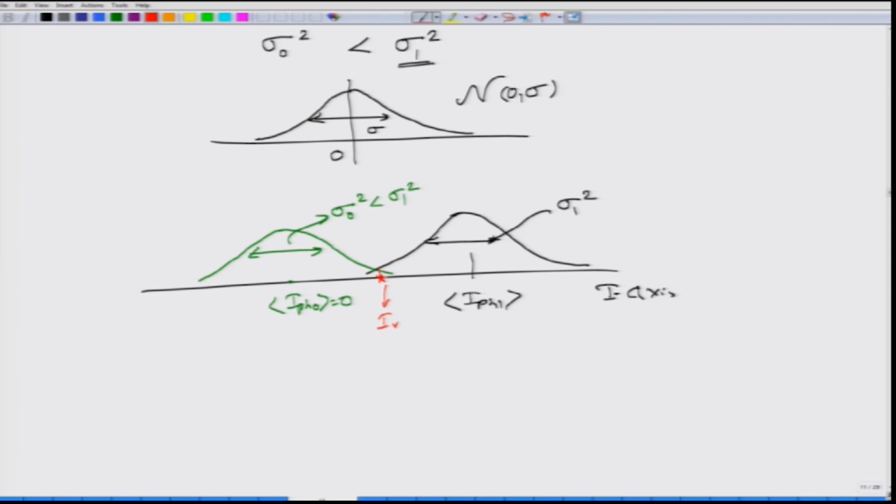There is a certain probability of this coming from bit 1, and a certain probability that it must have been just noise coming from I_PH 0, that is to say from bit 0 transmission. If you want to distinguish which is which and minimize the errors in that decision, you normally choose a certain threshold point. The way to choose it would be to choose the current at the point where these two probability density curves meet.